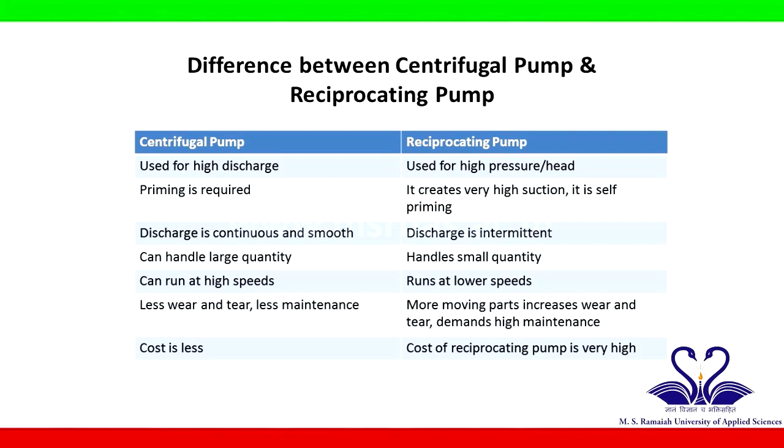Centrifugal pump can handle large quantity of liquid, but reciprocating pump can handle small quantities. Centrifugal pump has less wear and tear and thus less maintenance. However, in a reciprocating pump, there are a lot of moving parts and hence it demands high maintenance.